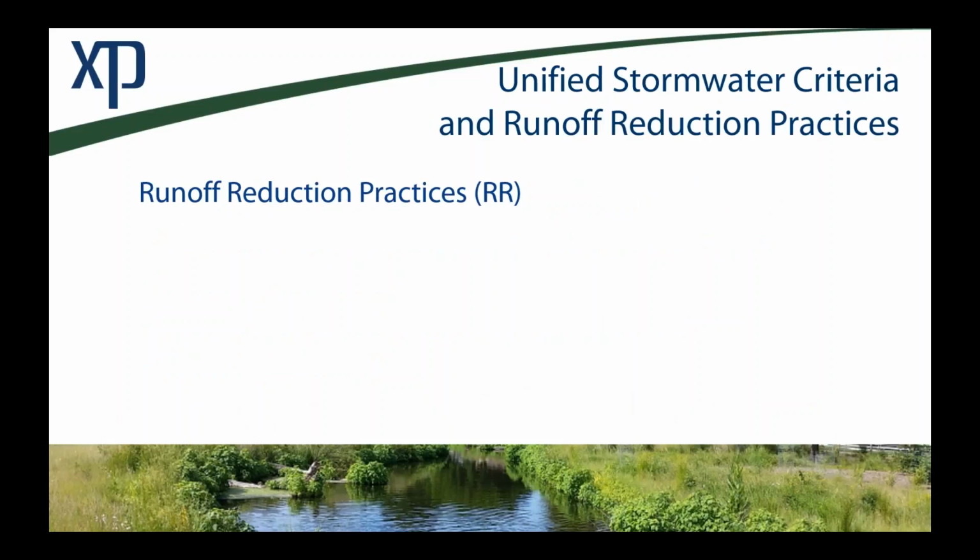As described by the Georgia Stormwater Manual, runoff reduction practices are stormwater BMPs used to disconnect impervious and disturbed pervious surfaces from the storm drain system. That's perhaps a longer way to say we don't want disturbed areas. We don't want pollution to wash into our storm sewer system. Pollution is going to accumulate on impervious areas or disturbed soils.